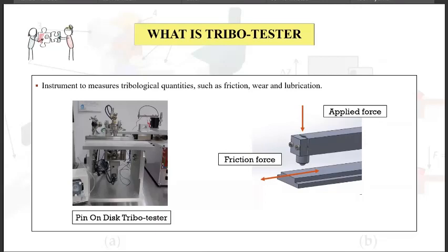As the picture shown below, this is one of the tribo tester in our tribology lab. The tribo tester that is planned to be developed is in reciprocal sliding motion, and friction is produced when the pin and slab slide against each other. The normal loading force is applied by using the loading mass, and the friction force can be measured from the sliding motion, so it will be easy to find the coefficient of friction to fulfill our second objective.